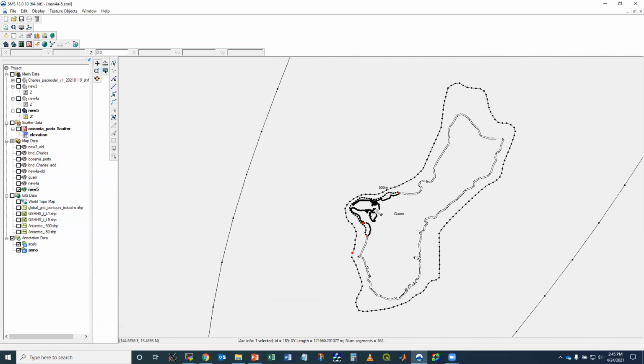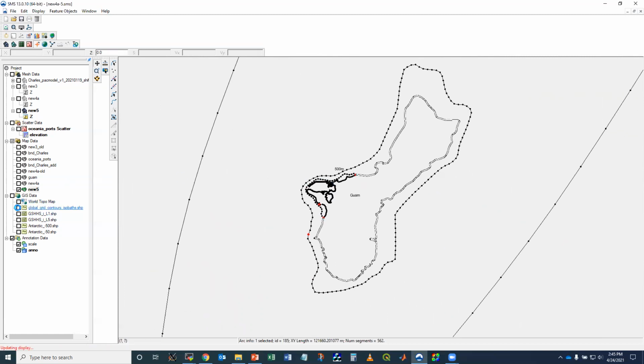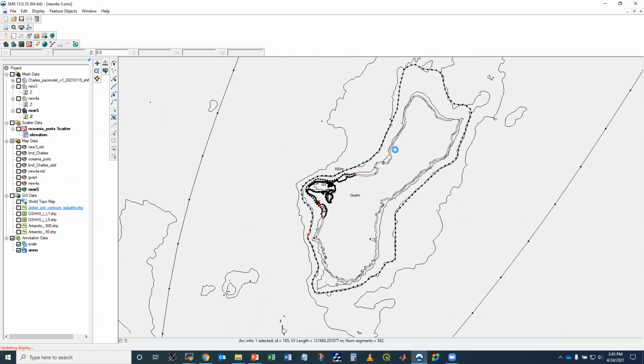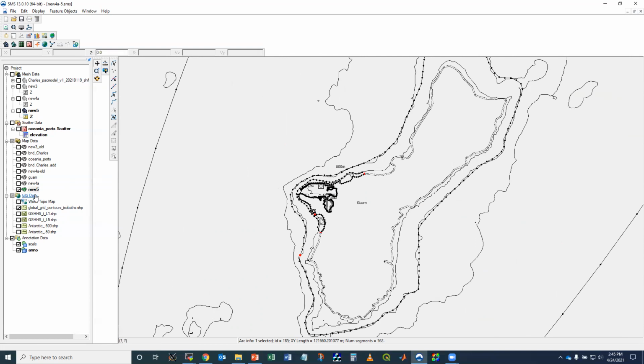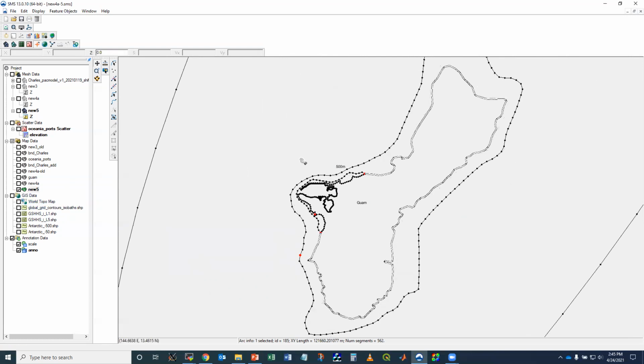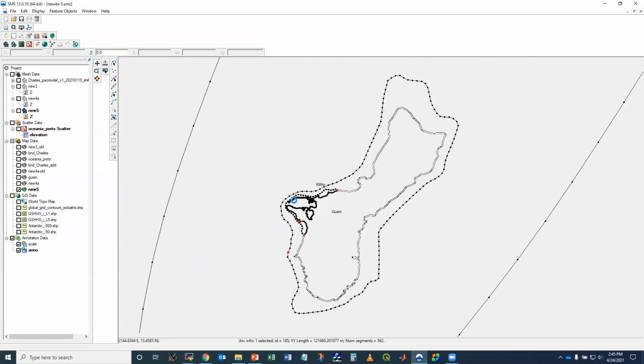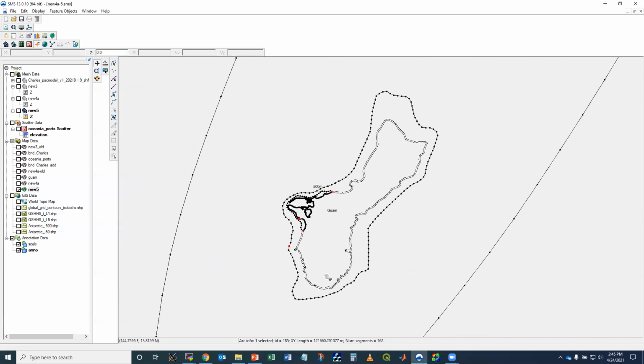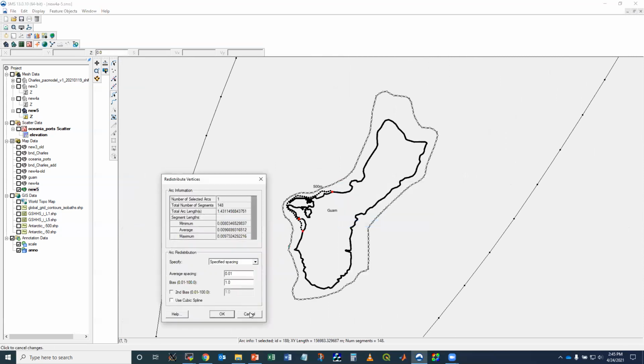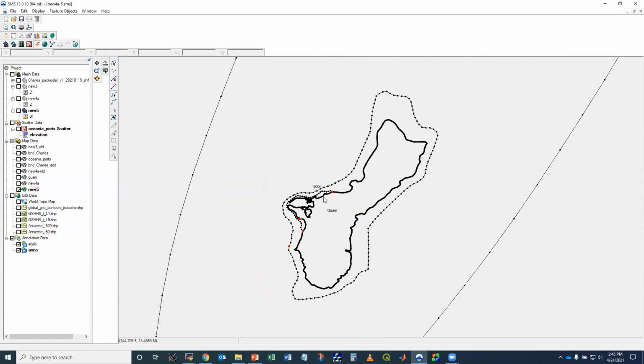So you can see in this case, if you turn on the isobars, it's actually quite steep. You can query this. This is actually a 500-meter isobar already. So a little bit away from the harbor, it's already pretty steep water terrain and deep water. So this is where we actually ended the auxiliary arc. This arc is a 10-kilometer resolution, I believe. Yeah, no, this is actually 1 kilometer resolution, 0.01. Okay, 1 kilometer resolution is still okay at 500 meters.